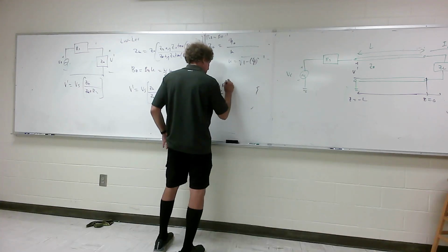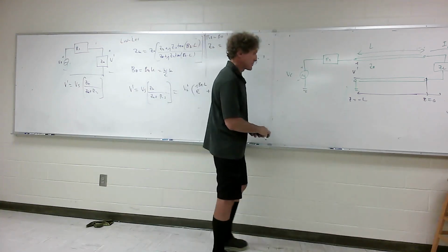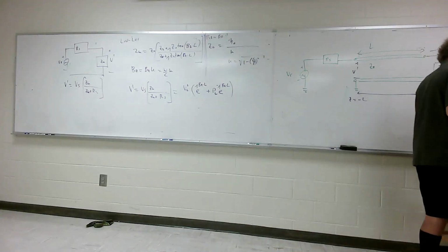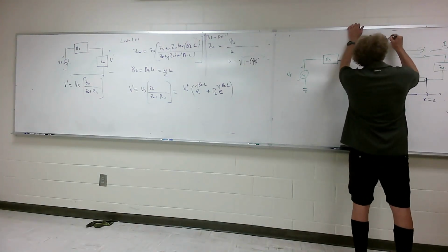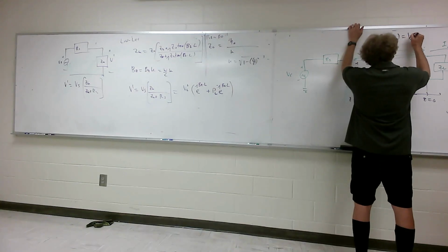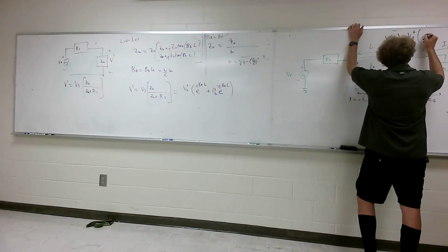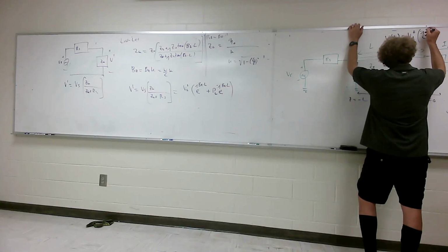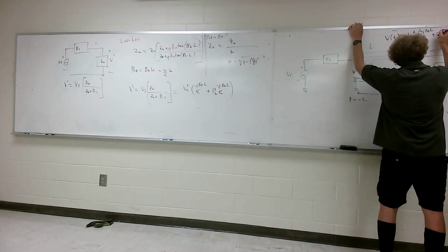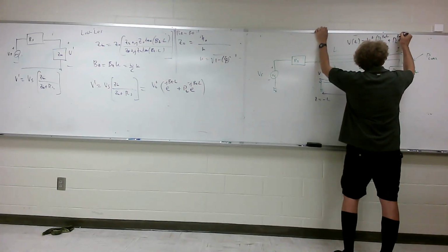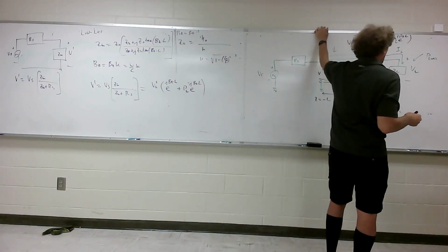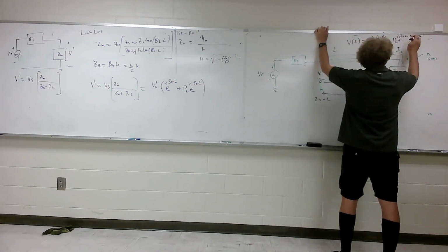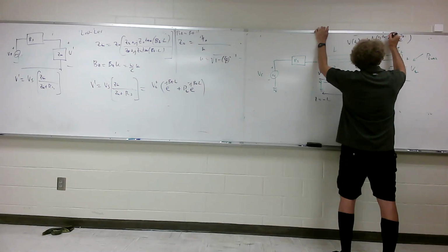Let me also state that for this particular transmission line or waveguide model, the voltage anywhere on the line is usually given as V0 plus times e to the minus j beta Z times L, plus the reflection coefficient times e to the plus j beta Z times L. Really not L, Z, pardon. I'm very sorry. Times Z.